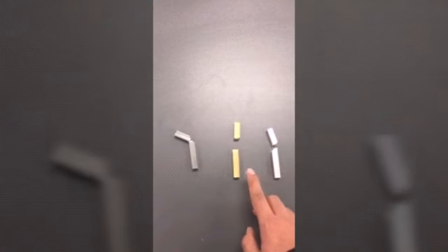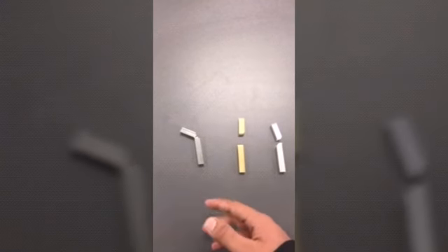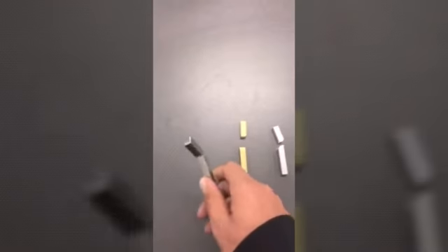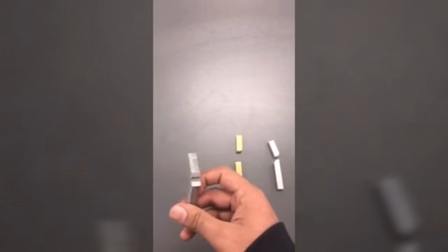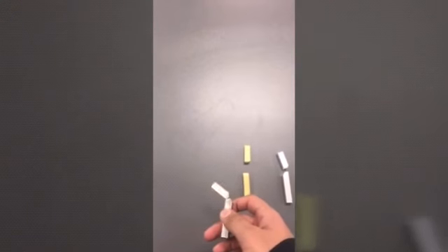So that's all the discussion. During the experiment, with the help of calculations, we can see the steel has the highest impact strength of the three metals. The brass and aluminum are the weakest ones. As you can see over here, this one is the steel, which is a little twisted, and this one is brass and this one is aluminum, which are totally broken. So brass and aluminum have less capacity compared with the steel. Steel is a malleable metal and has a shock absorption far better than the other two metals.